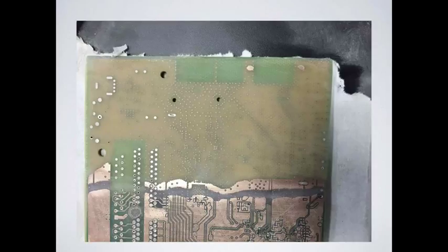So that's something that sometimes you really just want to take off the top solder mask. If you have a trace connecting 2 parts, but maybe they're BGA, so you can't get to the pins, but you want to sniff the traffic there, you just want to take off that top layer to get to the copper trace, and you can tap on the copper trace. So a little less involved. You'd be just taking off one part, but yeah. But when you have the components on and you're using these tools, that's going to be a little bit different. It's definitely going to be something you're doing by hand, using tweezers and little things like that.